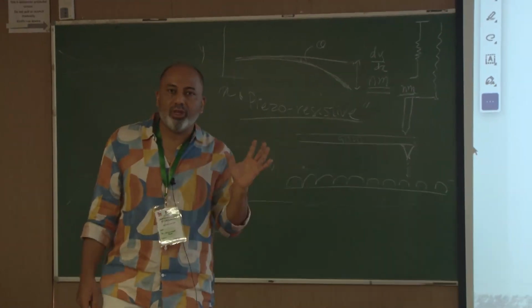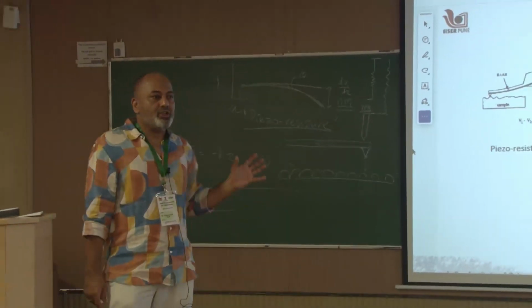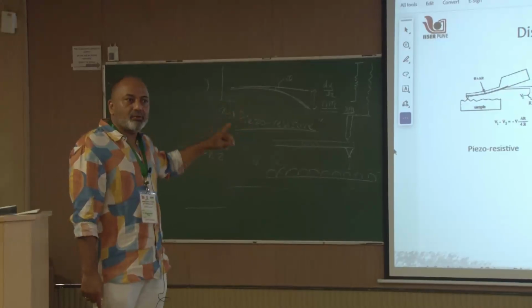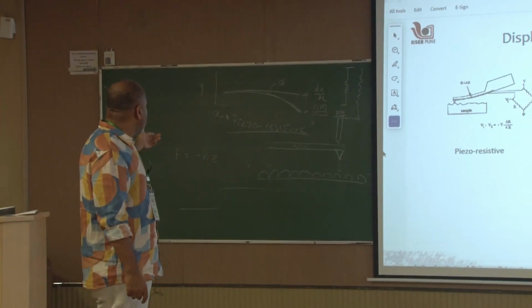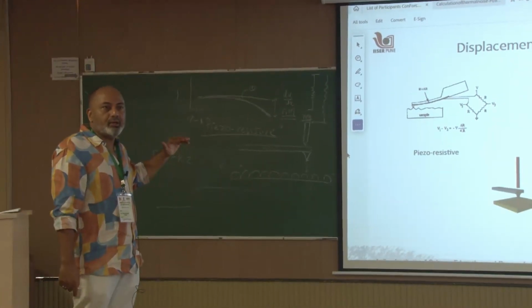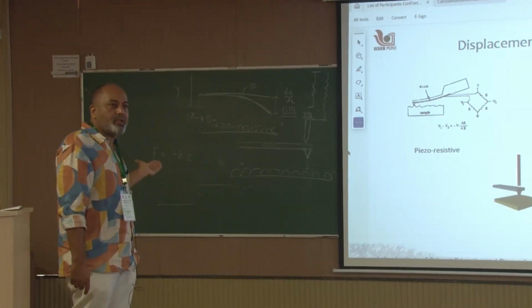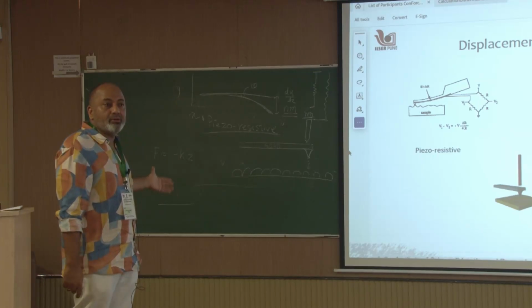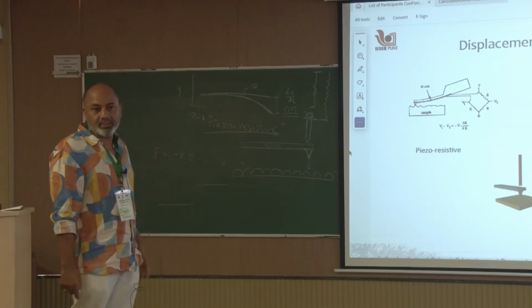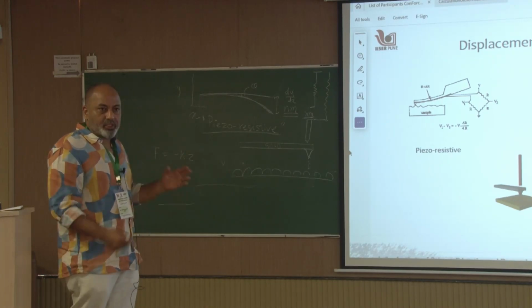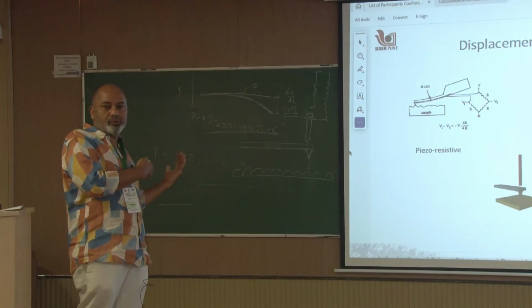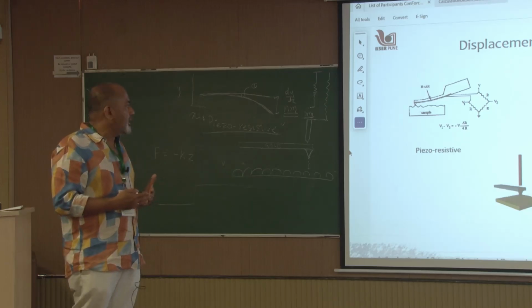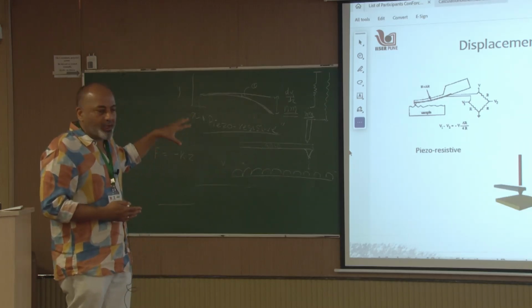So if you finally want to measure the force, you measure the drop in voltage, convert that to the cantilever's bending, and use Hooke's law: bending multiplied by the stiffness of the cantilever gives the amount of force that the cantilever has sensed. So this requires a calibration procedure, what voltage corresponds to what force in the end. That we will come to later on, how this is done.